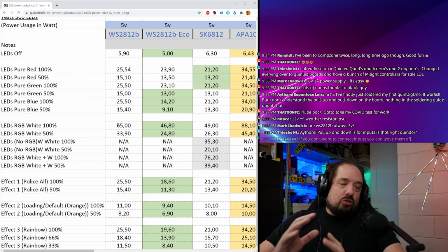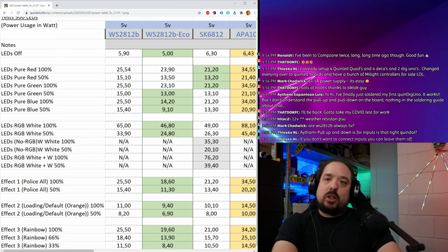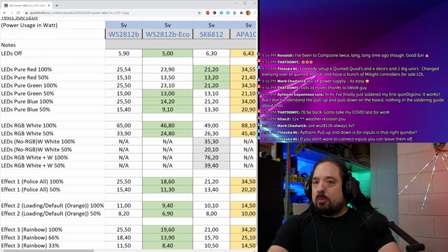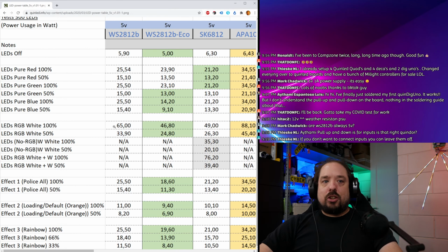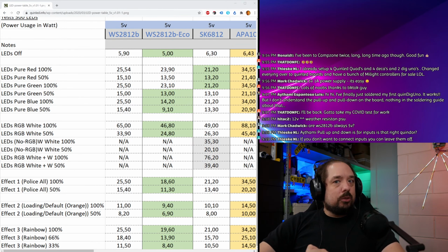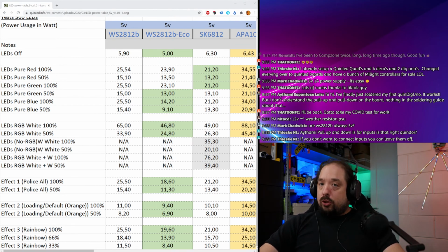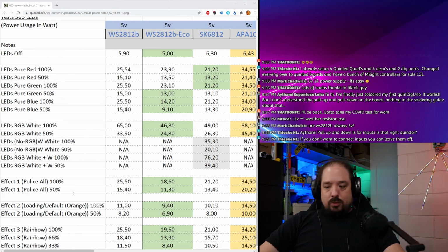So generally with 5 volt LED strip, when calculating power, it'll use about 1/3 of the maximum power. But let's say the maximum power is 65 watts. So let's be on the cautious side and say we need to be able to deliver 32.5 watts, so half of that. So, okay, let's say max power is 65 watt.